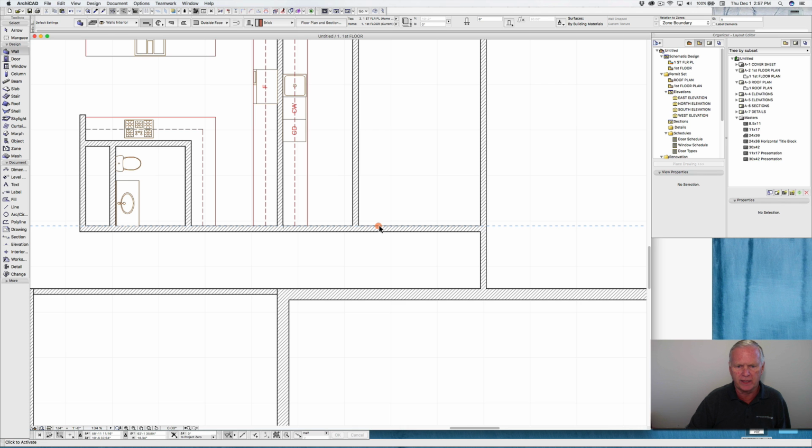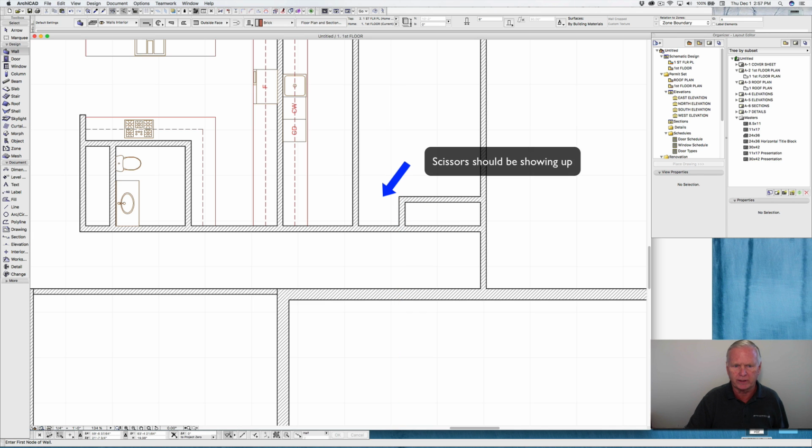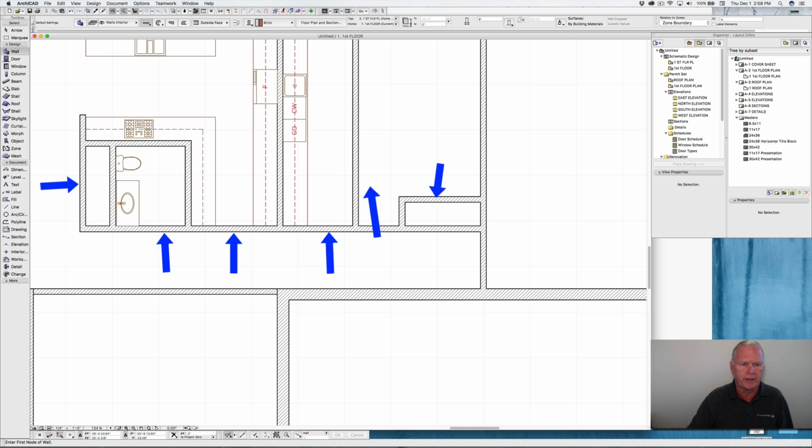We'll hover over this line, get our guideline D2-1, that's the line for the closet. Click over here, put in that wall. We'll have an entry area going into that, 3'6", and put a wall in like so. And let's get rid of that by command. The scissors comes up, we click, and it's out. So now we're ready to put in a swing door here, pocket door here, swing door here, bifold door here, bifold door here, and a cased opening here.